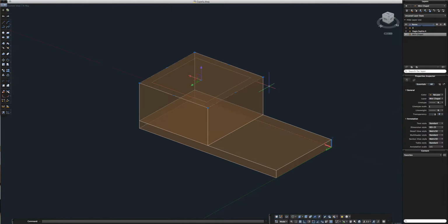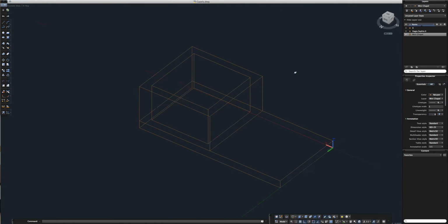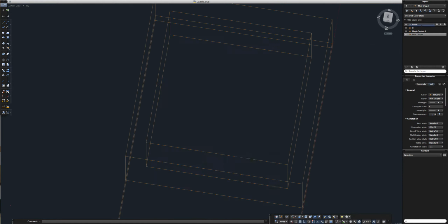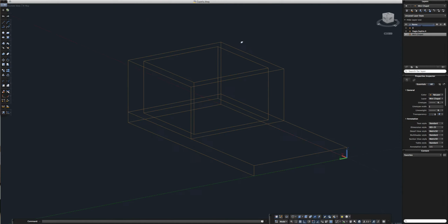Okay. Now we can get rid of our outer line, and now we need to make an extrude. All the way down. Now let's make a subtraction with the subtract command. As you notice so far, I haven't used or even changed our UCS. Yeah, now we have space to live in here. Okay.